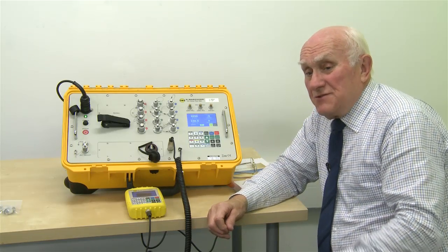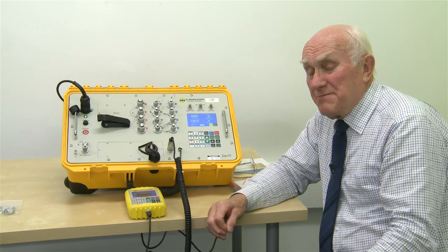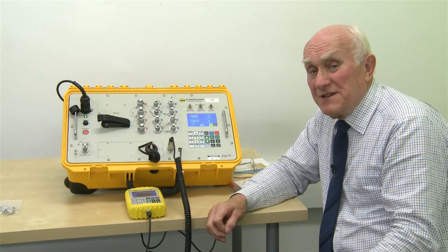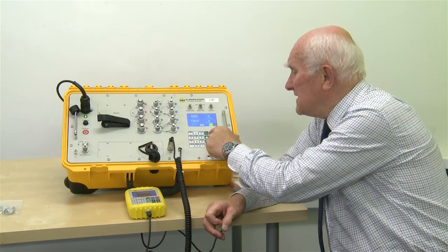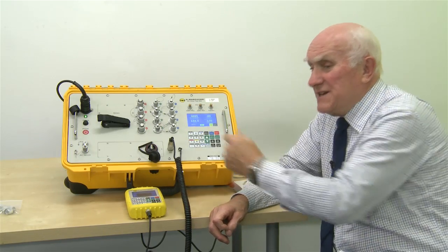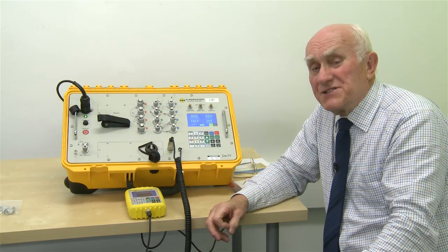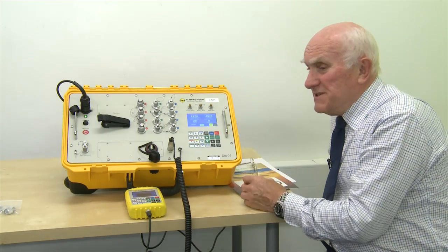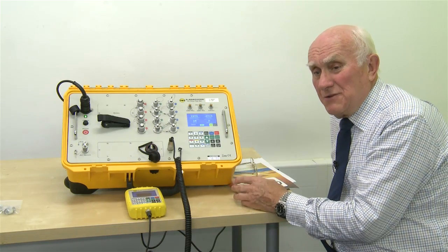Okay, when we've shown you all these different things, the obvious final step is to vent the instrument down to ground. And we have the shift key and vent, and automatically the system will take itself safely down to ground conditions at safe rates. When the instrument is safe at ground, you're finished. You can pack up the unit.